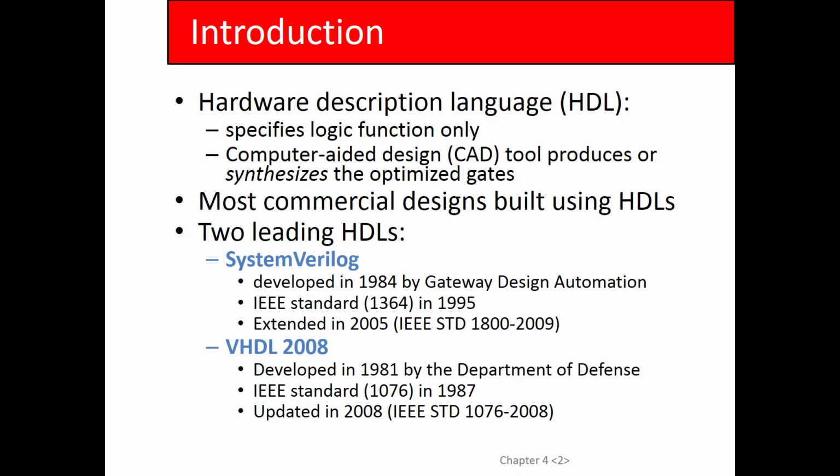And that's what hardware description language is all about. But the problem is that there is a fundamental thing about HDL that makes it hard to learn: hardware description language is a high-level language. It's like Java or C or Python. But you're generating hardware from it. So when you compile it, they don't call it compiling with HDL, they call it synthesis, because you take the program and you're converting it into gates and registers.